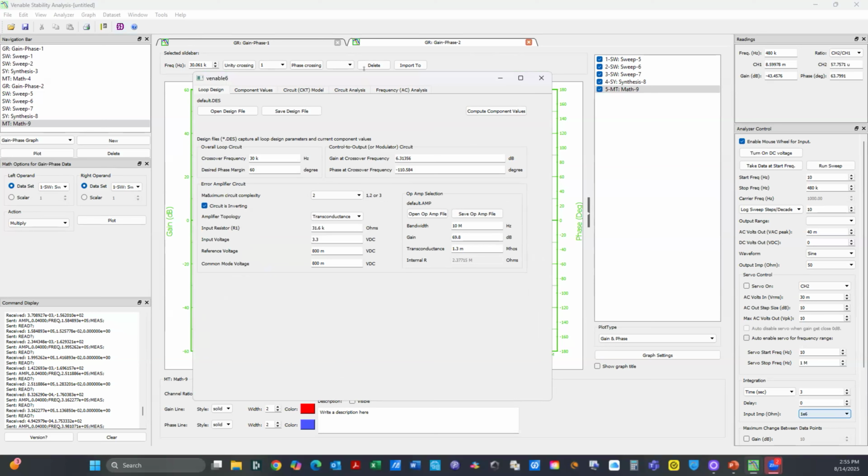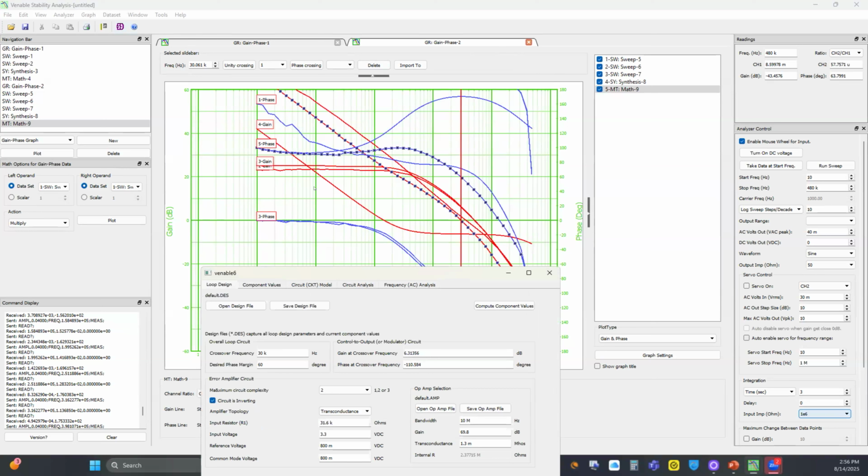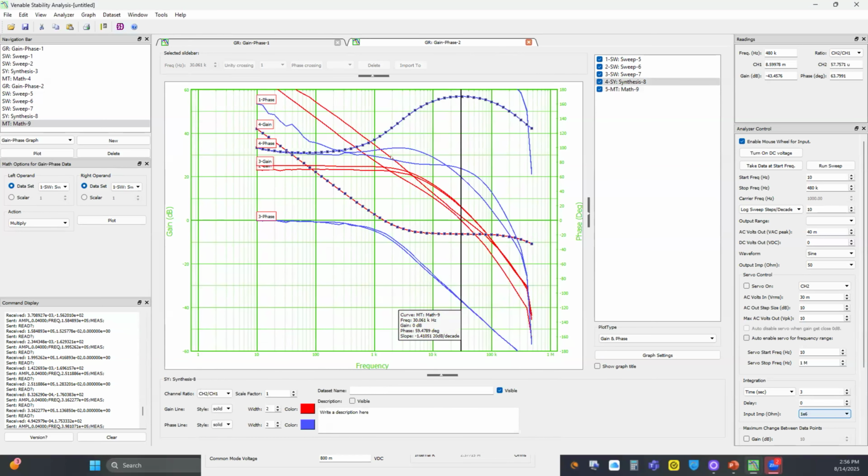So I'm a little curious about how we get to this step. So let's say I already have a design, a board with these values in. Oh, okay. Well, you could measure your feedback loop, or I mean your error amplifier, if you were just curious. You can measure the power stage, or you can measure the error amplifier, you can measure the entire loop. So it's up to you. You could actually measure all three and see how they're going to work.